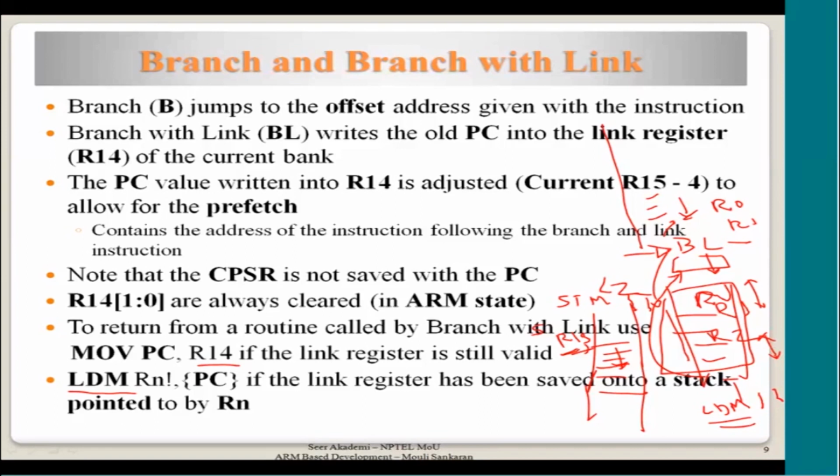the same set of registers, so that the stack comes back here, and then you do an LDM PC. In this PC, what you will do is write R14. That means the value is copied from whatever is there in the stack, which is actually stored in R14. Because suppose your R14 is saved here, that R14 you will be copying into PC, so that you come back to this location. So the PC is restored by using a stack instruction.